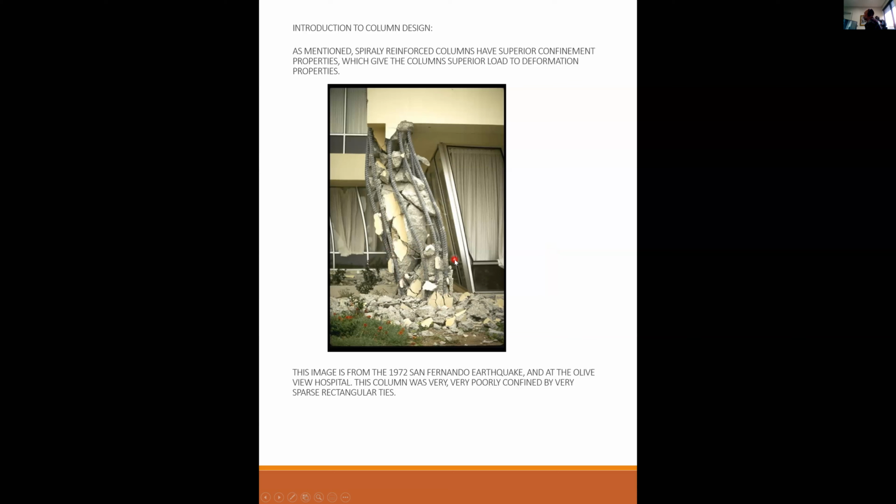And perhaps what you might see is the spalling and the cracking so severe that the rebar inside of the column, you can actually see it starting to buckle on you. Those would be signs under a gravity condition, and that would be something that you could see for weeks and months and years before it might actually get to the point where it collapses. That would be something different. But for lateral load, like a hurricane or an earthquake, it goes from pristine to destroyed in a matter of seconds.